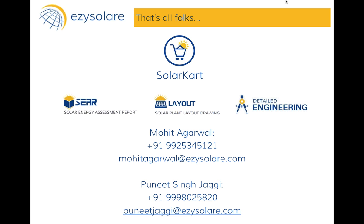The next question again by Mr. Vishal. In comparison of PR and generation, which guarantee shall I ask of the EPC? Well, if the EPC contractor is very desperate, he'll give you a generation guarantee. But ideally, you should ask for a performance ratio guarantee. We have seen typically in India, the theoretically assumed radiation is actually lesser than the actual radiation that you get on site. So if you have got a reasonably good PR guarantee, you might be able to hold the EPC contractor responsible for a higher generation number also, right?